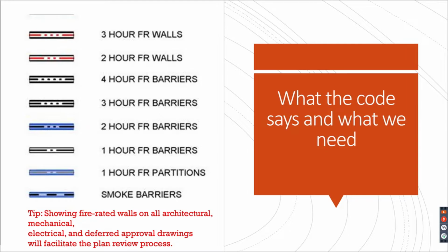We have had recently actually a project that went through design, plan review, and into construction, and the wall was called a 1 hour wall. And it was built as a 1 hour fire partition, but it was required to be a 1 hour fire barrier. So maybe the designer assumed everyone looking at this knows this is going to be a 1 hour fire barrier. Maybe the plan reviewer assumed the same, but the individuals on site constructing the wall, they did not know.